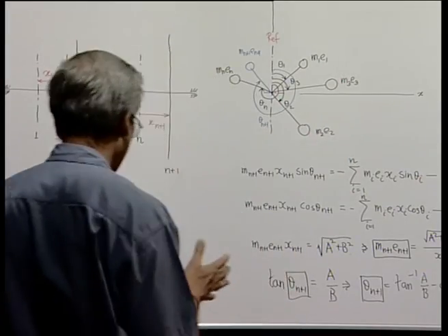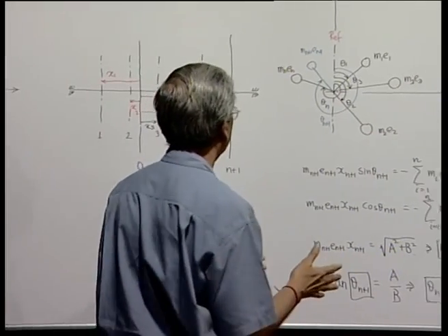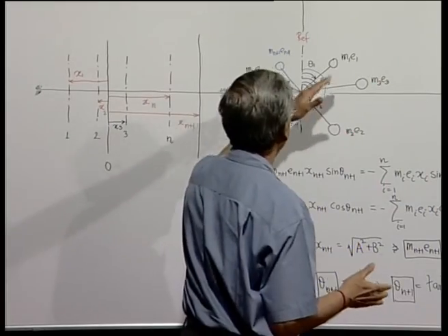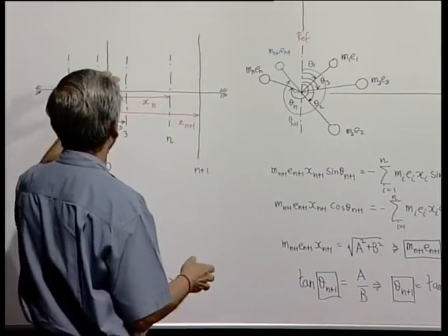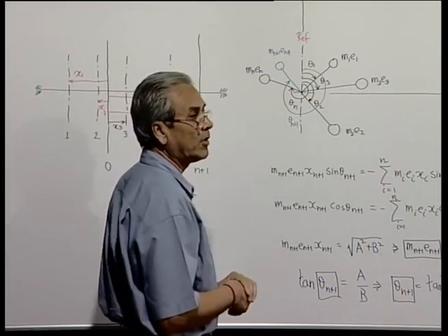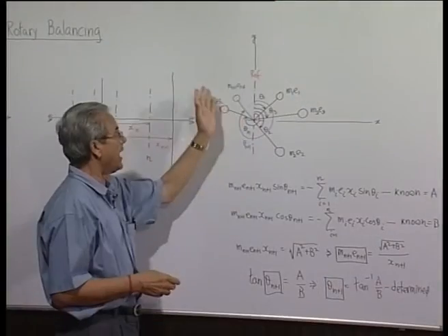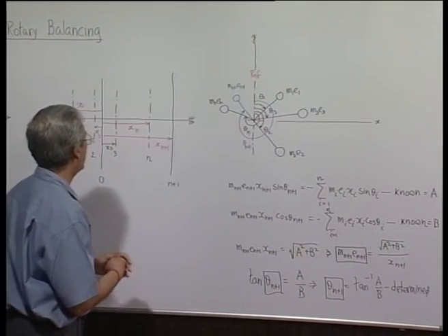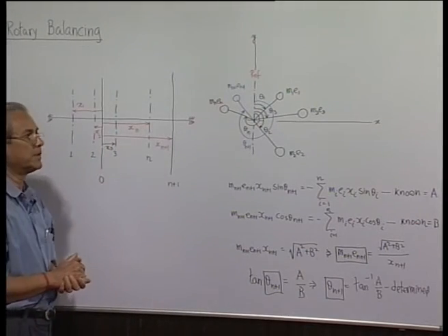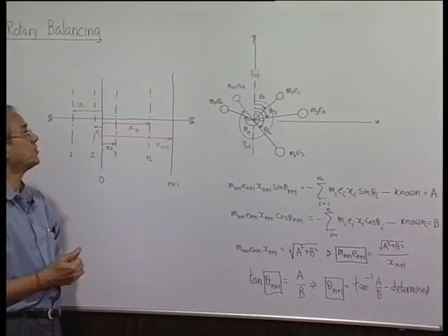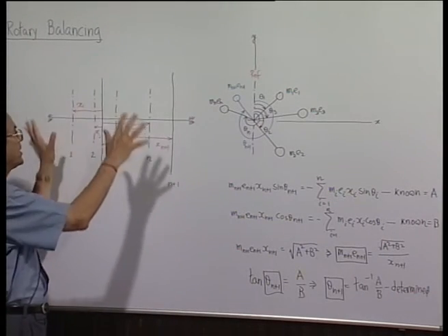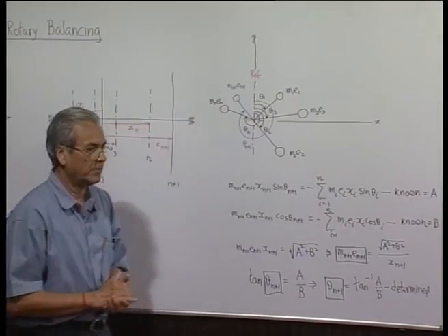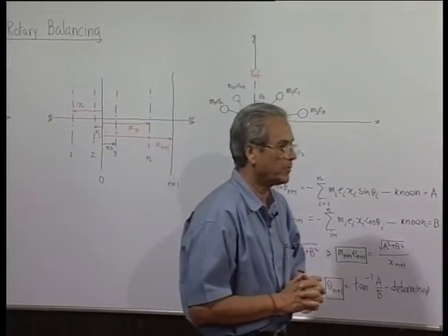So, this is the way at the design stage, when the designer knows the kind of various objects coming and the centers of mass of the various components coming, it is possible for the designer to identify two suitable balancing planes and to put suitable balancing amount, so that the whole system is completely free from any unbalanced inertia force.